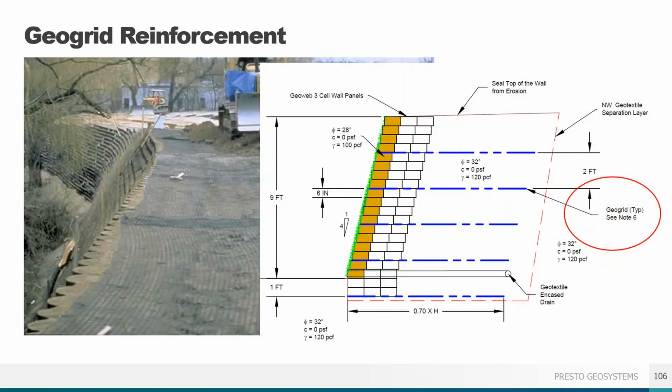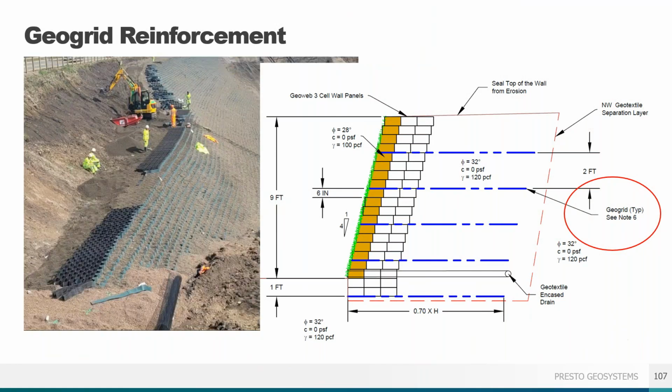Many of our earth retention project evaluations will incorporate grid reinforcement and call out specific strength characteristics and spacing. Most geogrids will be uniaxial, primarily for cost purposes. Make sure they're installed in the correct direction and appropriate minimum strength. For uniaxial grids, that means perpendicular to the wall face, since the grid only provides strength in that one direction. Again, when in doubt, talk with our engineering team and make sure you have it right before the install.